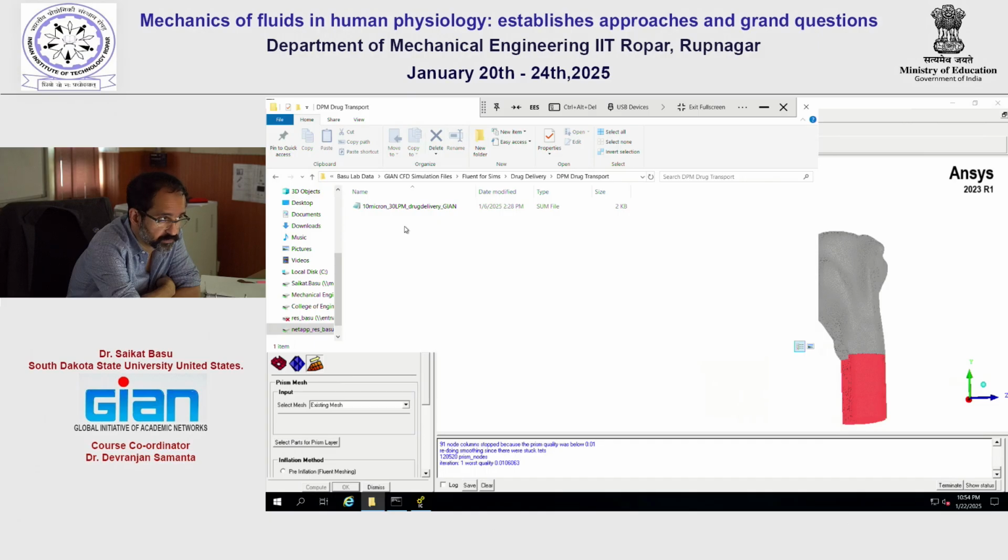works. Are 10 micron particles just treated as some points? Let's say you are putting different size particles, how are you assigning the size? So the size dependence only goes into the drag force calculation because it's a function of the diameter. But otherwise, because the particle cannot impact the flow field, it is a point particle. So you just put some points and then do random tracking.